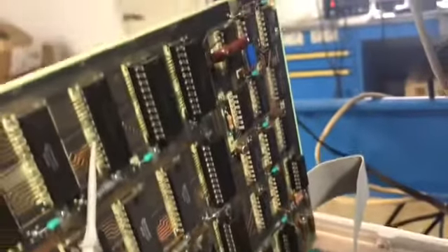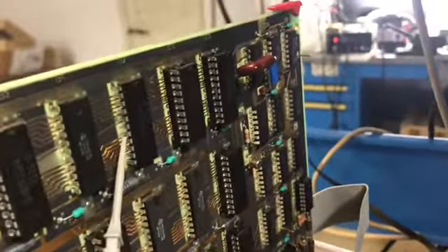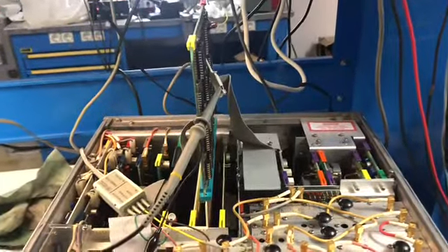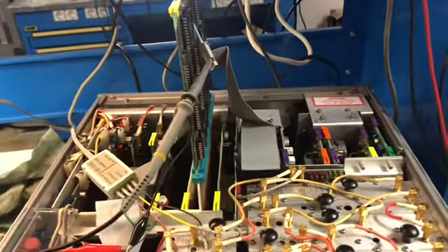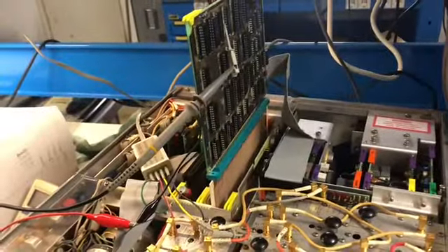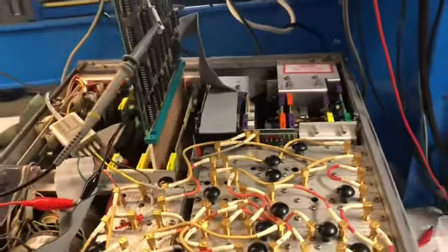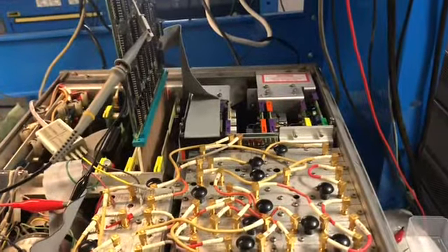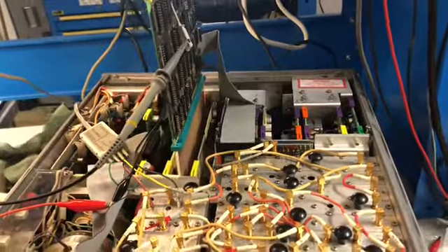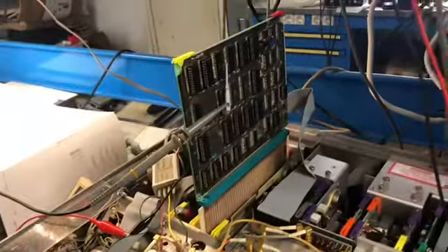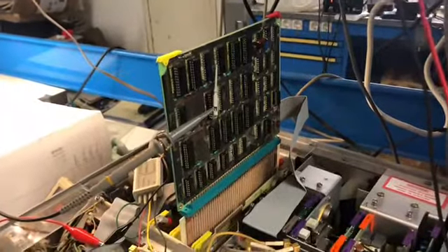So it seems that here we have a lot of oxidation on these ICs. So what I'm going to do is to try to solder the legs in a way to make them contact, since I don't have in my hand right now the new ICs, and then see if I can fix it, and after that of course I will replace those ICs. So let me try to fix also the second one.